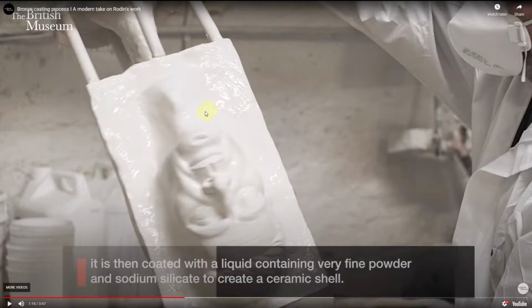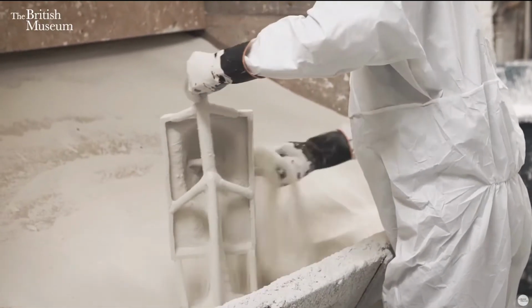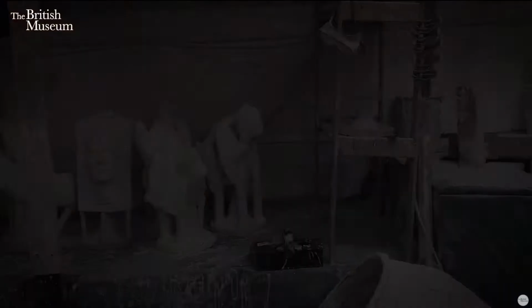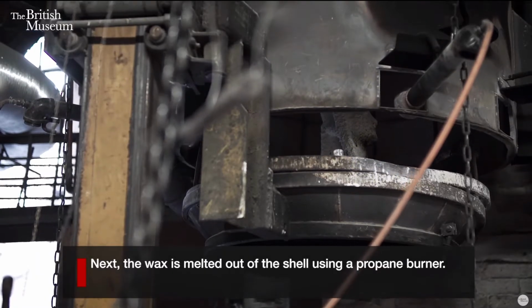And he's gonna keep on putting silica to create a mold around it. And you do this multiple times until it creates a really thick form around it. See how thick that is now? Then you put it in the low melt kiln like this to just melt out all the wax, so that you create a void, a hollow mold inside where the bronze goes in.